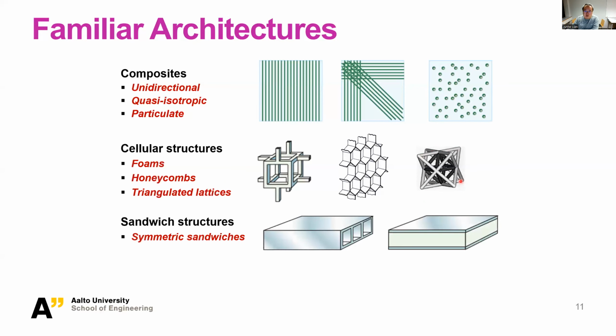And we also have the sandwich structure. There are two different kinds of sandwich structures you can see here. This is the symmetric sandwich structure. Of course, it can be asymmetric. So basically, we will not have two equal-sized layers, top and bottom, but different thickness or different volume fraction, and also possibly different areas in case of certain applications. So these are some basic architectures of hybrid materials. And there could be many more.